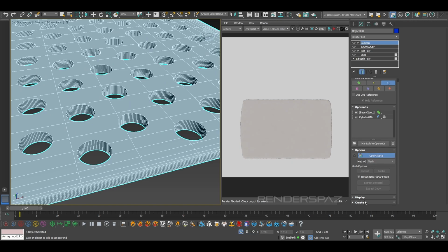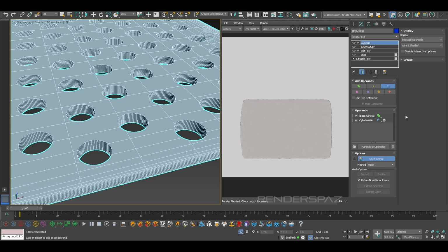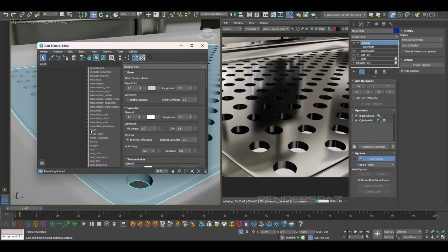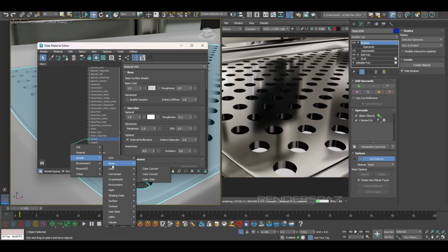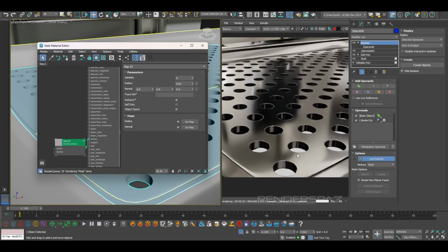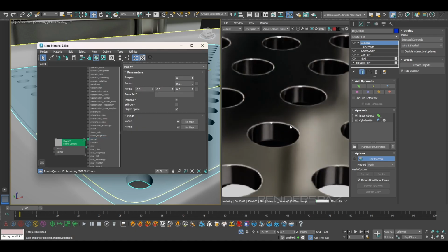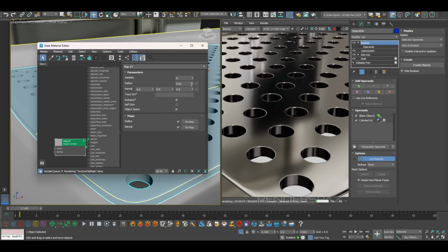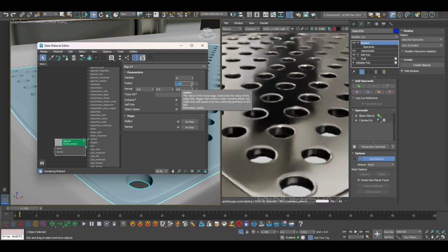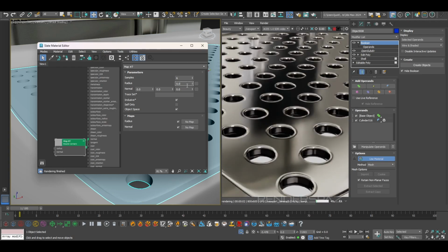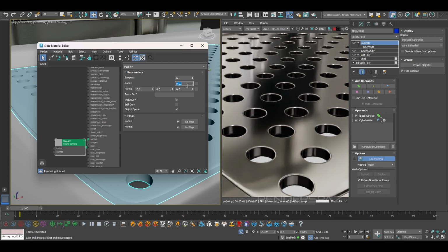And I would say let's use maybe a chamfer towards the edge, but I got an idea. We can use Arnold's round corners. Let's do that. Okay, so we'll go into our material here. We're going to go to our normal, and go to bump, and do the rounded corner node here. Okay, round corners. And we can play with the radius a little bit. 0.5, 0.2, and you can see that we get a really good result here without even having to mess with the mesh itself.